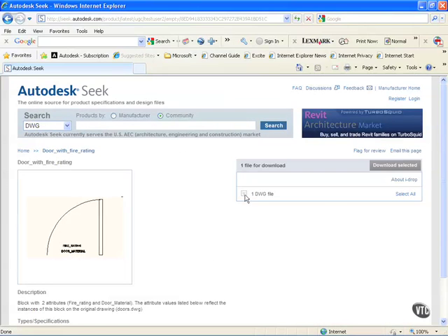If I click on this little down arrow here, it now shows me a little DWG file with a little pipette. That pipette indicates that it's an eyedrop piece of technology. Eyedrop is here, or you can click here and find out about eyedrop if you want to, but what it is, it's a plugin for Internet Explorer that allows you to drag and drop Autodesk content into AutoCAD from the internet. So I tick my door, I want to drag and drop that now into my drawing.